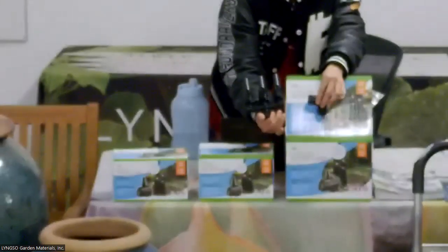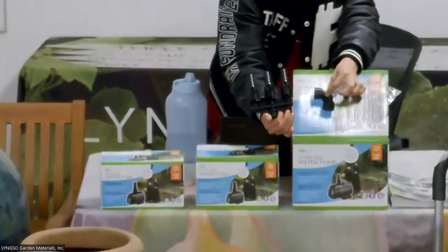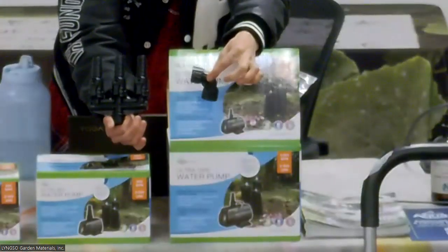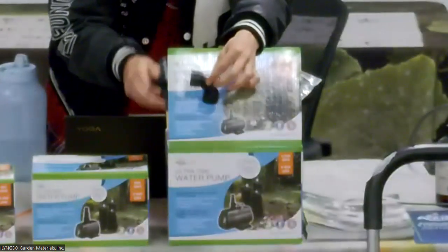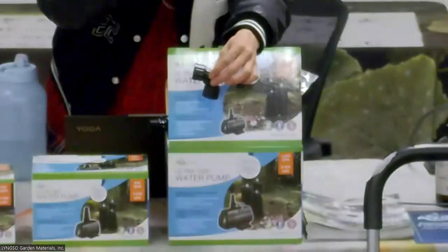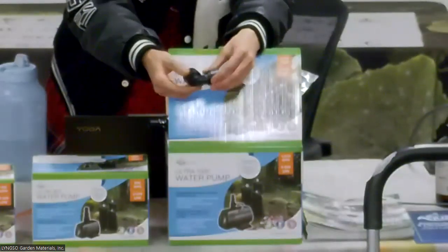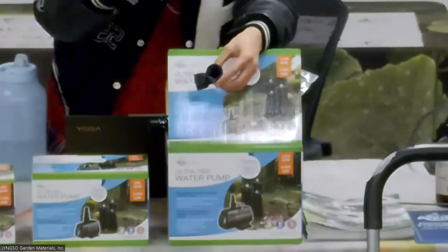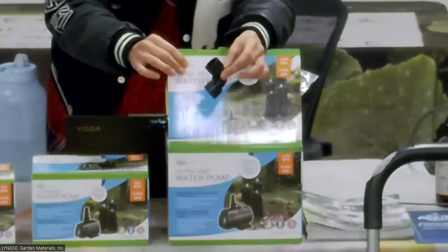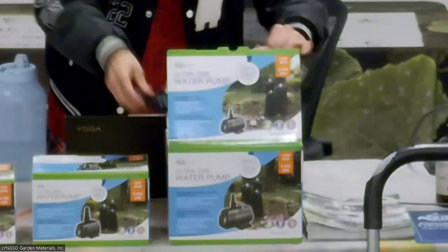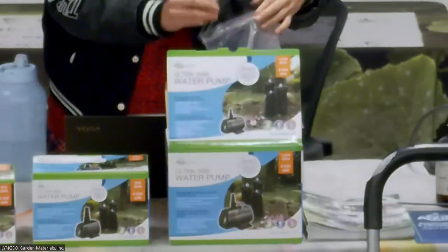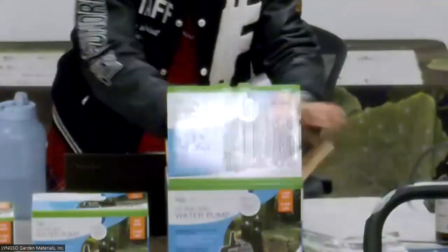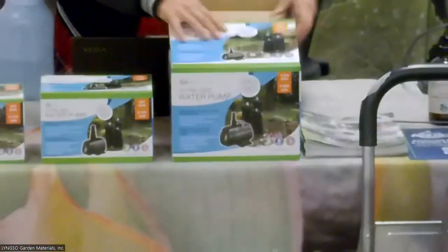This piece right here is very important. I didn't go over it in the PowerPoint, but a lot of times it's an elbow piece. When you place your pump inside of your basin, you don't want your piping to go straight up from the pump. You want to angle it so that it doesn't kink or get hit on the top. So that's what this piece is for, and I didn't go over that. But yes, there are no further questions.